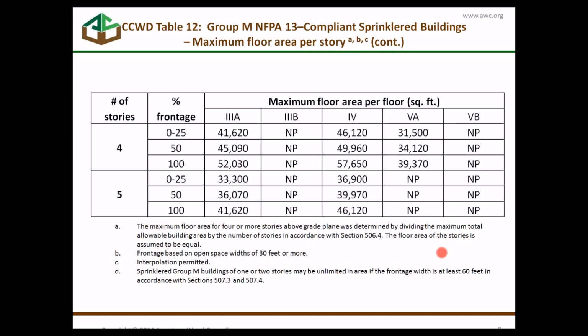That will be that with the allowable increases, you can see at a quick glance the actual allowable area of a building with the increases already calculated in, with the allowable size per story already calculated in. You can see here that for 5 stories in the building, they get bumped down from a 4-story building and so forth. We have some very helpful footnotes in each table.